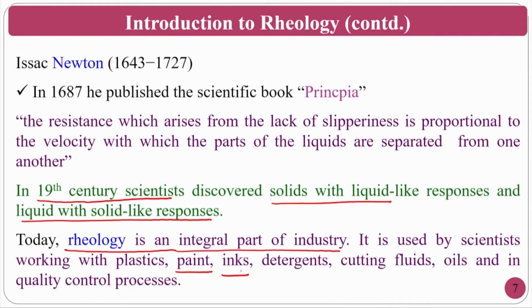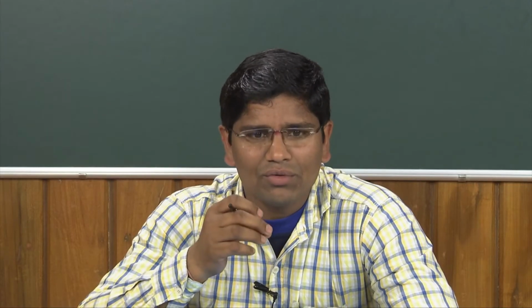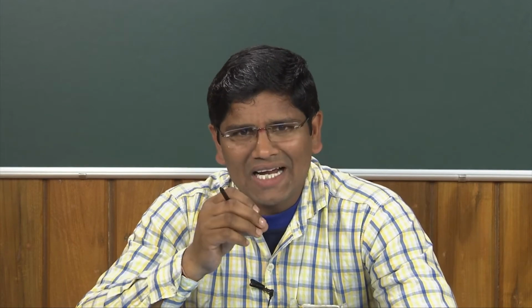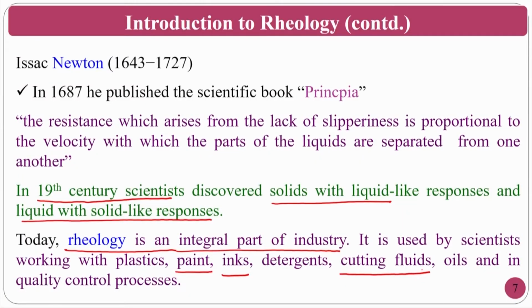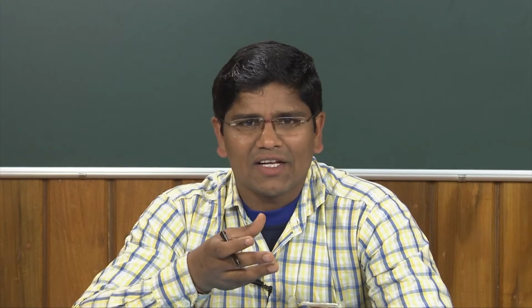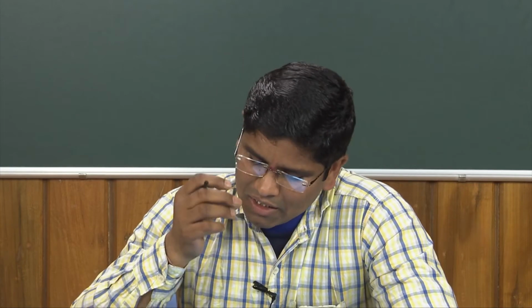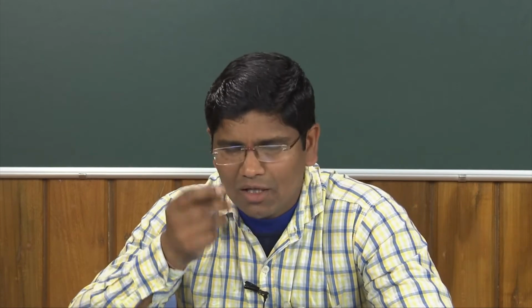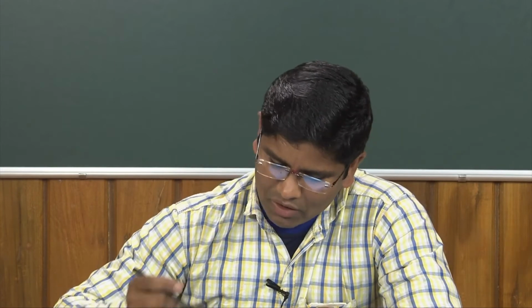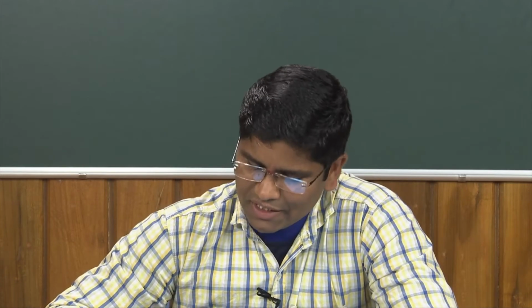Like bio inks and inks also there. Nowadays people are talking about 3D printing. People talk about 3D bio printing. So you have to deform or flow the ink along with the cells properly, otherwise you cannot make a complex surface. Similarly, the cutting fluids also are one type of these suspensions, because people nowadays are talking about nanofluids and other things. If you take the nanofluids, that is what you have seen in the previous classes, these are the cutting fluids or the emulsions with nanoparticles. So this also resembles your paint or your pharmaceutical creams and all those things, but with low viscosity. That's why it is more important to study the cutting fluids from the point of rheology.